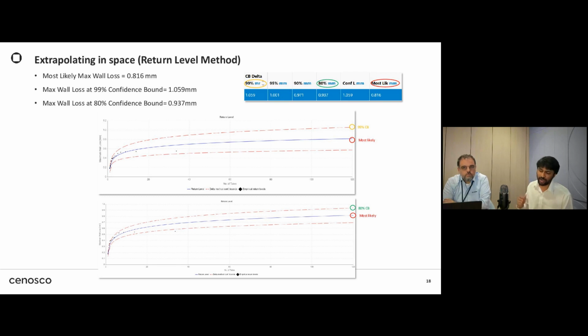It's because there were a number of qualitative inspections done in the past, a number of borescope inspections, and that was revalidated using IRIS inspection in 2023. And a good understanding of their wall thickness results was typically identified. And it also typically validated this thesis as well, because historically they had some level of qualitative data. And on quantifying these data in 2023, they did not expect something out of the blue as well. So that was a good finding with regards to the inspection that was carried out.